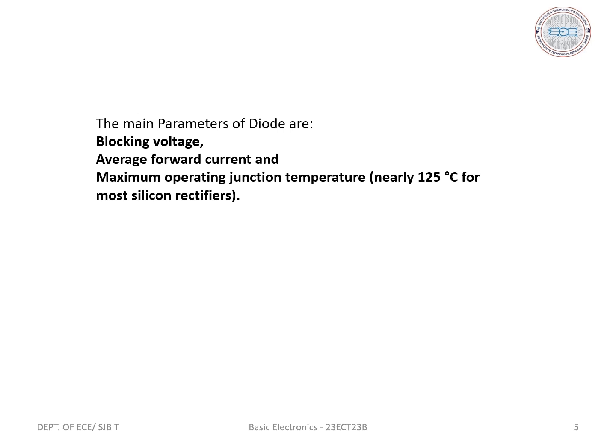Next, we have reverse breakdown voltage. It is the minimum reverse voltage at which the PN junction breaks down with a sudden rise in reverse current. That is, VBR is around 50 volts for a germanium diode and 75 volts for a silicon diode. Next, we have peak inverse voltage. It is the maximum reverse voltage that the diode can withstand without destroying the junction.